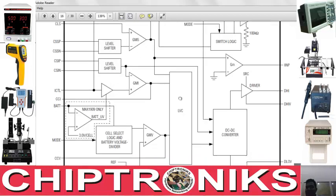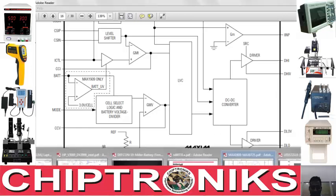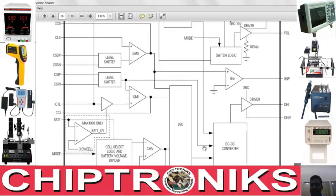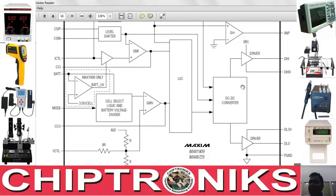It will generate a signal to control the timing of DHI and DLO, which is going to the gate of the MOSFET, external MOSFET, not internal. These are external MOSFET. DHI and DLO is generated through the internal op-amp. You can see over here, it is generated through the internal op-amp.